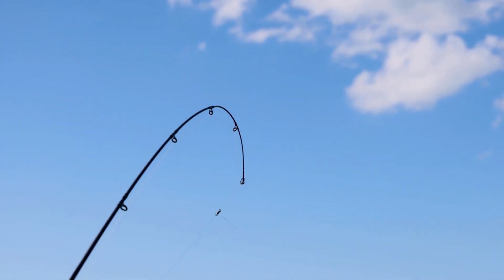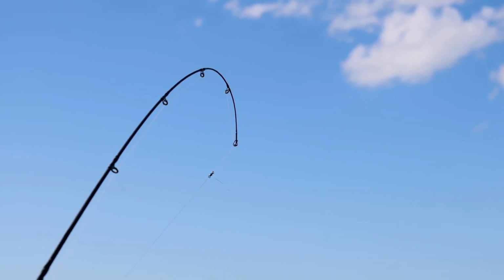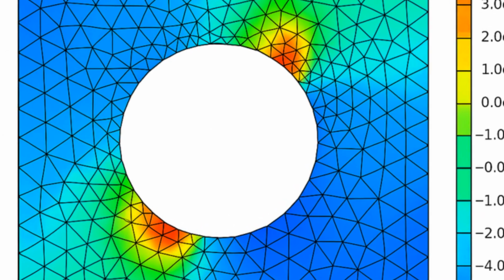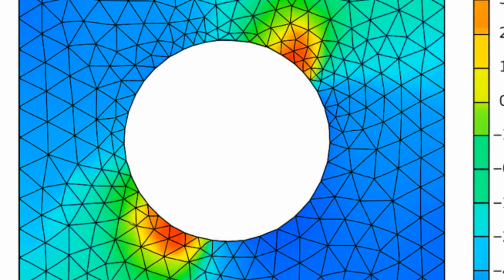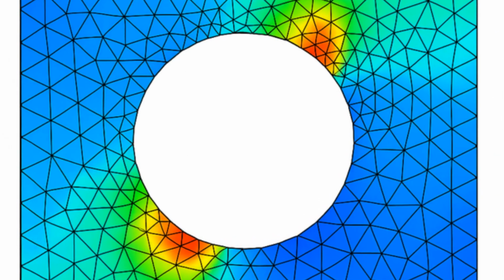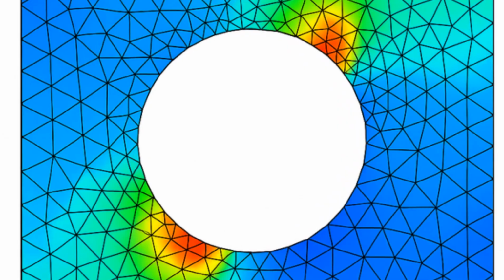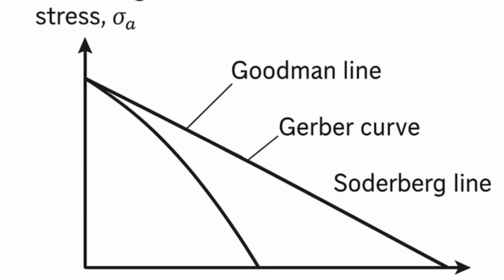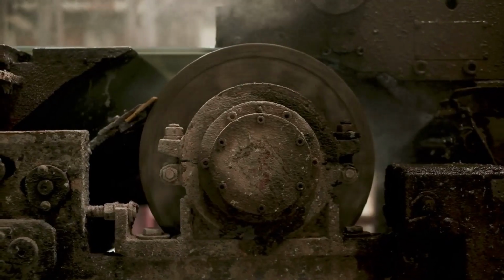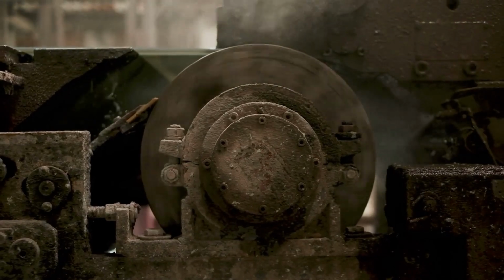It can also handle large deflections and contact between parts. This gives us a very precise map of the strain distribution, especially in those critical high-strain areas, which is essential input for an accurate epsilon n fatigue calculation. Another vital consideration is the presence of mean stresses. Most real-world components don't just cycle around zero stress or strain.